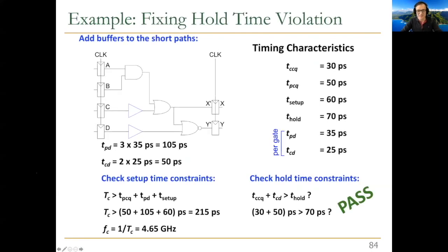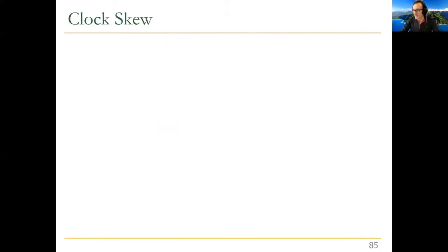So remember, this is where we are. Basically, we looked at sequential system timing, and you need to make sure you obey the setup and hold time constraints in a sequential system to make sure that everything works. And these constraints are really determined by the sequential element timing, which is flip-flop timing. Those are based on when you actually sample the data while the clock is rising, right? So that's why this is really important. But clock skew actually affects both of these timings, as we will see.